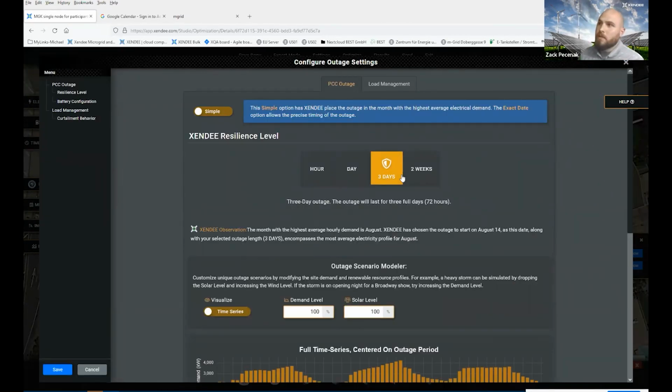Yeah, as anybody who works with microgrids knows, there are two major value streams. One is cost, which is probably the rarer one for which a microgrid makes sense. The other one, the major one, is resilience. And this is where the Department of Defense has really identified itself, in the resilience space. The point is, what does resilience mean? Resilience means responding to outages, responding to contingencies where you don't have power, and having the microgrid actually become a microgrid. So the way we model that is by specifying specific outages and letting Xendee know what assets will be available and how it should respond.